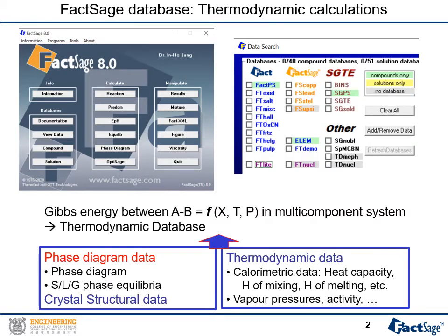Our research group has developed the FactSage thermodynamic database using the CALPHAD methodology. For the CALPHAD type of thermodynamic database, we evaluate all existing phase diagram and thermodynamic property data simultaneously and critically, and prepare one set of Gibbs energy functions based on the most reliable experimental data. In this process, phase diagram information is one of the most essential data for good thermodynamic database development.